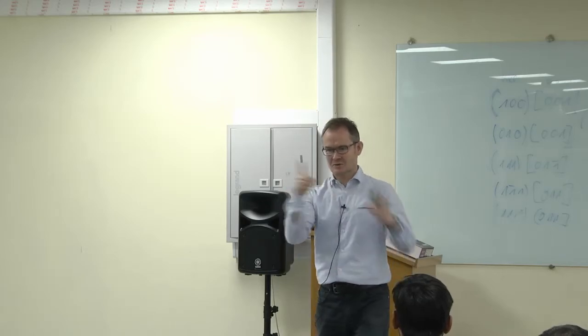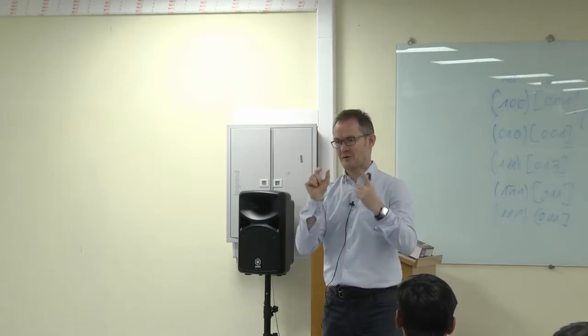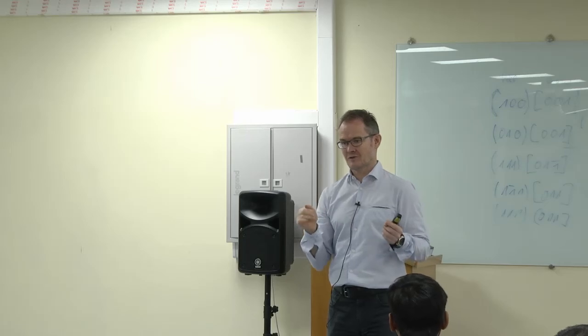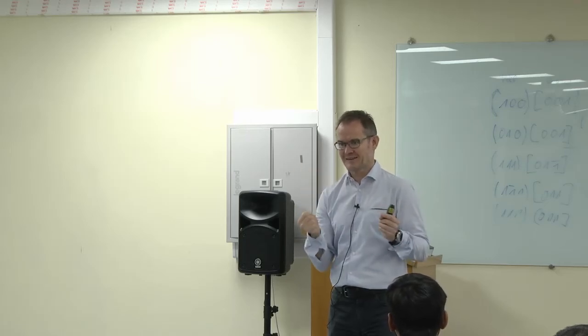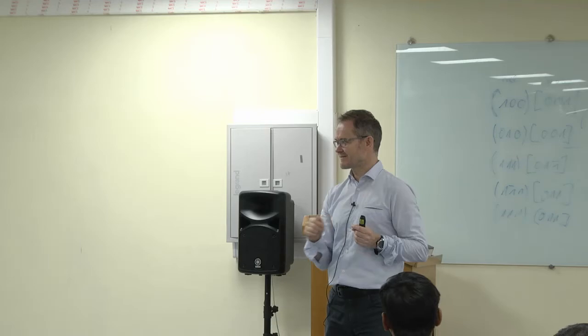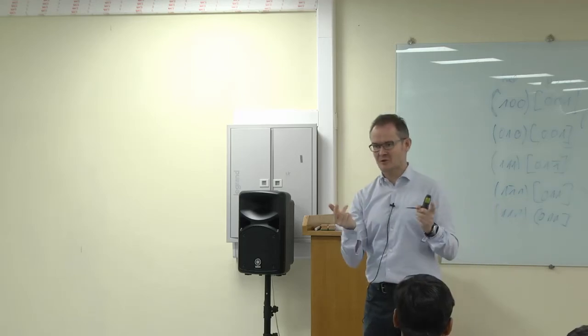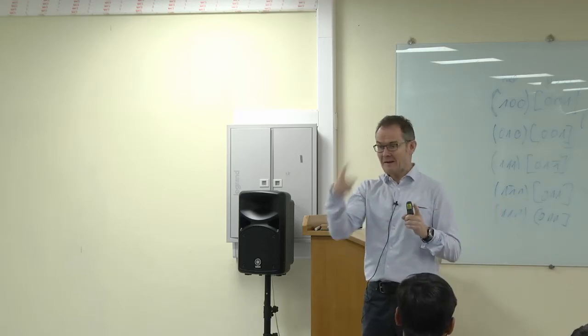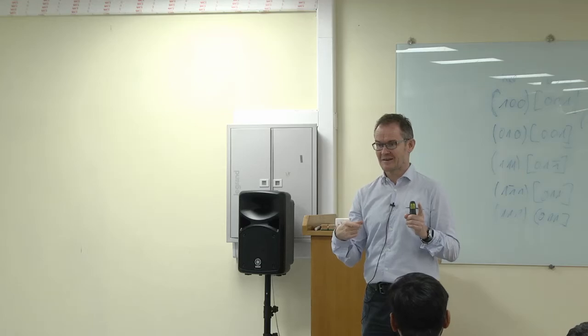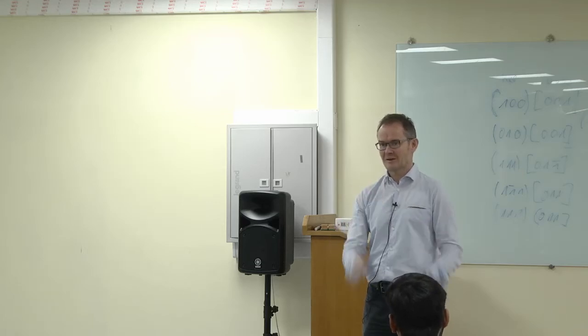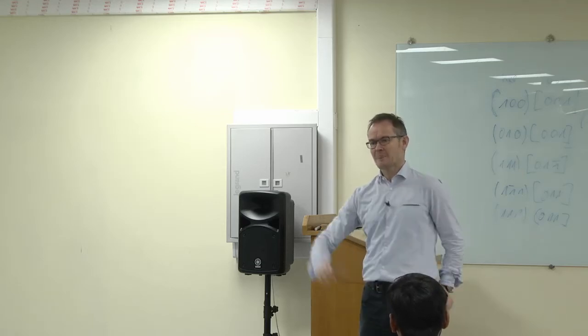A misorientation between 2 points has, in a cubic system, 500-something symmetrically equivalent representations, how many? 24 times 24, exactly. And in the software, all these calculations are done for every point. And you wonder how they can make it so quick.